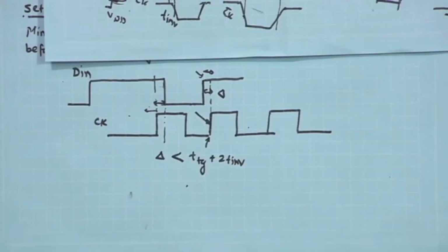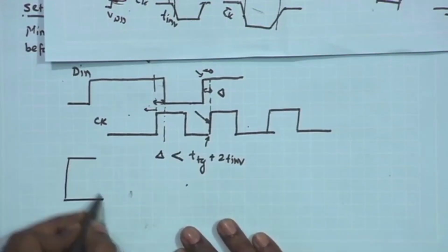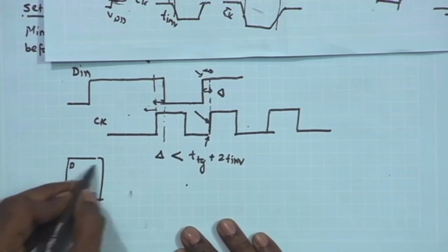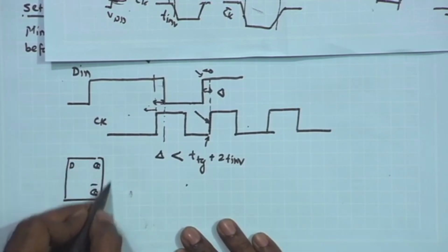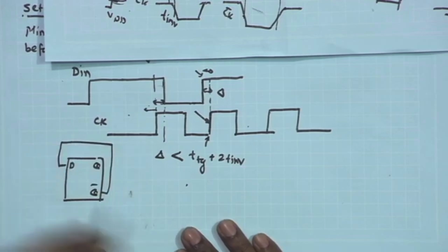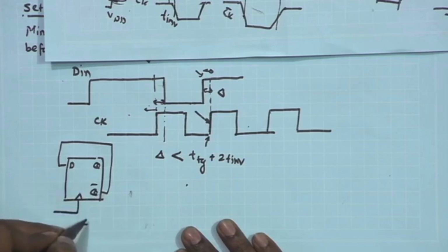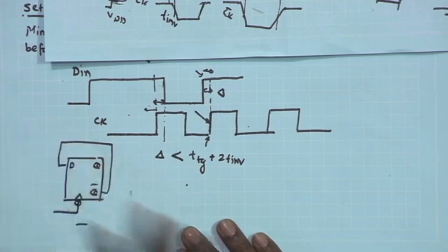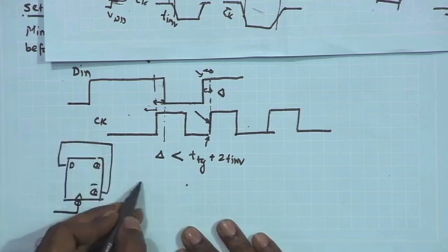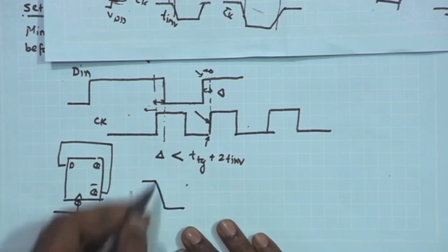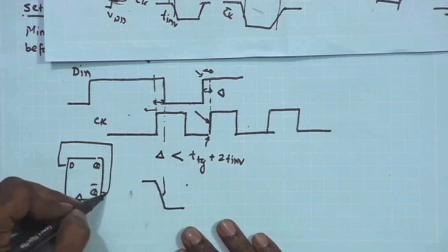So, if I see where we are applying this, you have the toggle flip flop being constructed, with D, Q and Q bar, and we know that Q bar is connected to the D, and then you have the clock. Each element in my design has the Q bar connected to the D, and therefore, before the edge, in our case we have used the negative edge trigger, just for the up counting operation. So, before the negative edge comes, the Q bar is anyway stable, right.